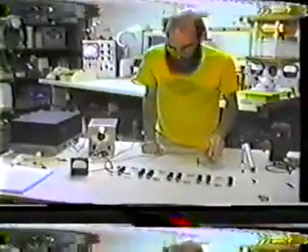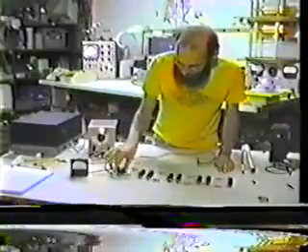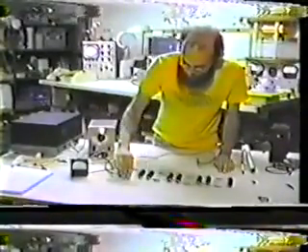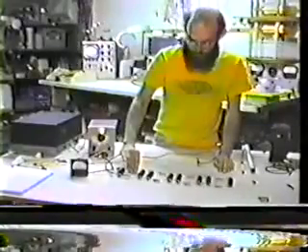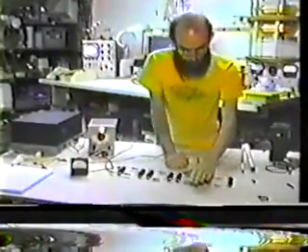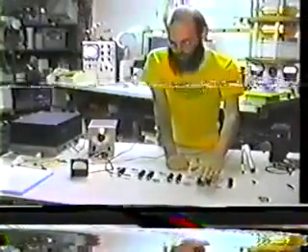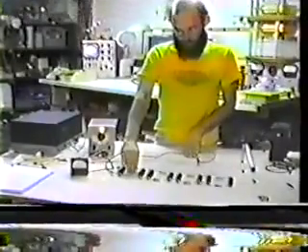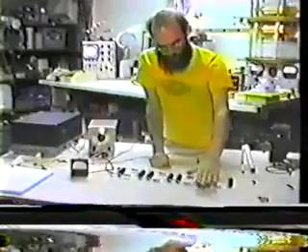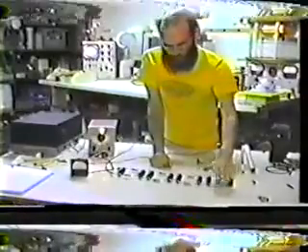And we'll do our heat check again, see where the heat's coming from in here. Feel our input coils, relatively cool. The input capacitors are quite hot. Go down the line here, capacitors are cooling off, but the coils are very, very warm, this end. So now we have the situation where the heating effect is turned around from where it was before. Now the dielectric input capacitors get hot, and the magnetic output inductors are getting warm. So we have quite a few differences here. Now what we'll do next is some quantitative comparing of these differences, and then we'll do a few novel experiments and give some ideas for the experimenter to work with this on his or her own.